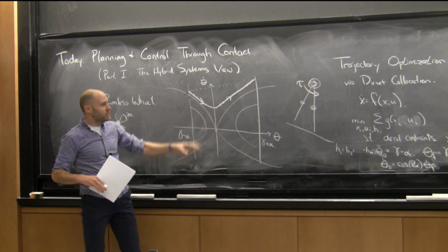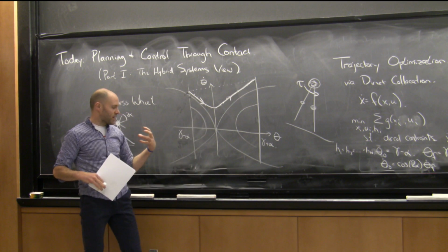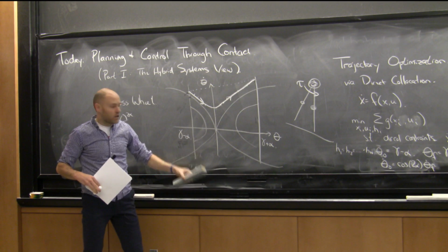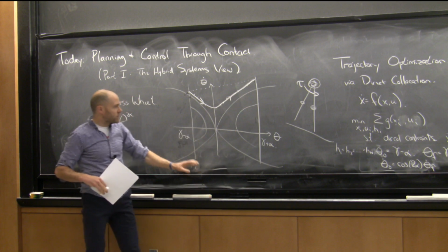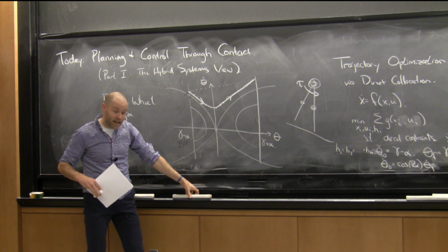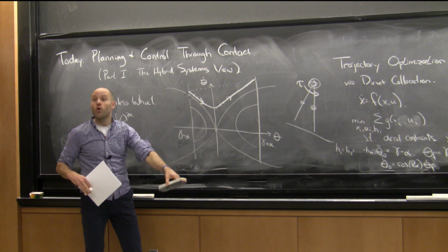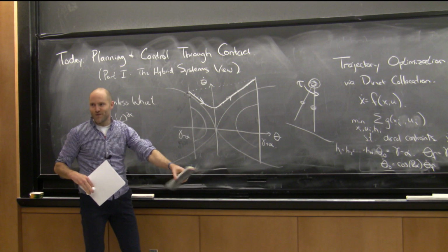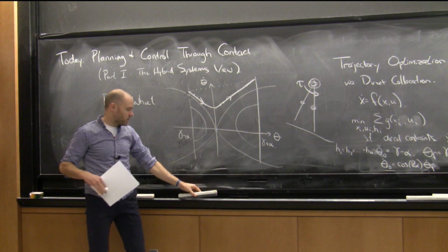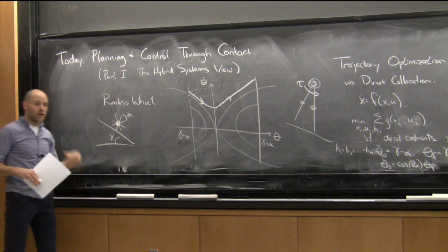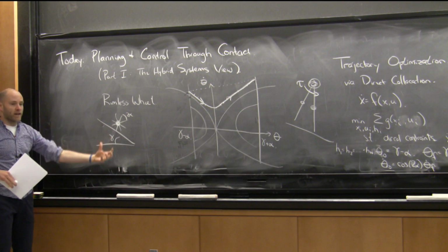For our system, if we write the differential equation that describes both the robot and the object, then the equivalent of this trajectory optimization problem, where you include the contact dynamics between the hand and the object, and ultimately maybe have a new goal for the object, that's the interesting planning problem where the dynamics start to matter and the impact on that dynamics. So when we talk about planning for manipulation, we're going to actually move the object.